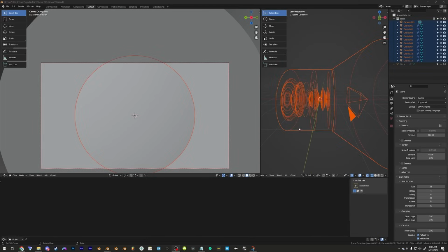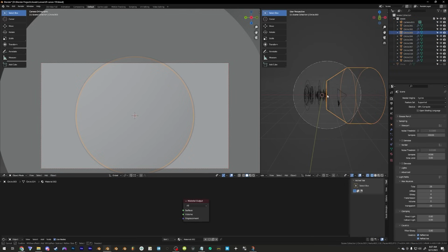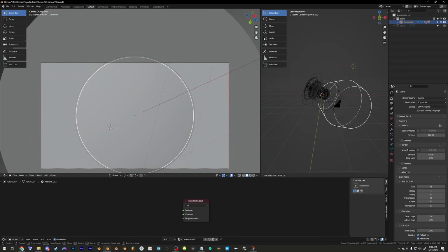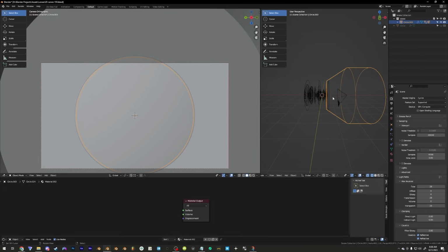There was a step I had forgotten, which was to parent all of these objects to one object. That way, it's easier to transport them around. So set parent to object, keep transform. Now we can just move our camera around, and it's doing everything we needed to do. Also, ignore the random frame drops in my Blender. That's because my VRAM has pooed itself due to the crash.